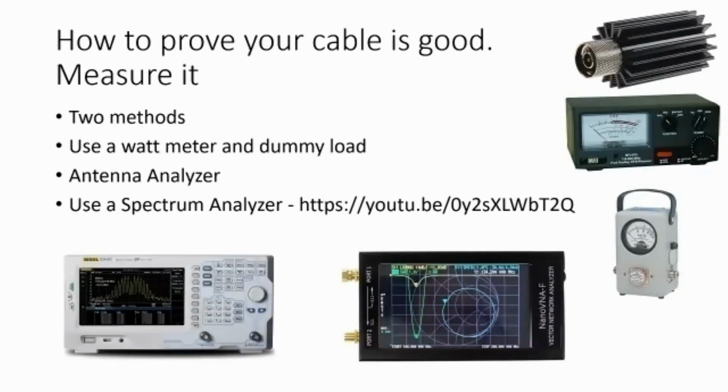You can use an antenna analyzer. Many devices like the nanoVNAs that have come out will measure cable loss. They work very well when you connect them to the software, because you can then specify the type of cable you've got under test, and they will measure the loss of a piece of cable.